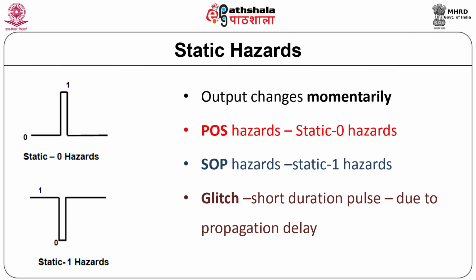Here the output changes momentarily when it should not. The static 0 hazard is also called as POS hazards, and static 1 hazard is also called as SOP hazards.